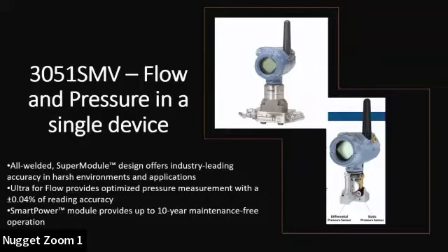There are other process variables that we send out, including your power module or battery strength. We also send out a health status. Is this process variable stale? Is it active? So these are things that we can do to help make sure that you have a pad that is getting back real information in real time, and also that the data you're collecting is good.